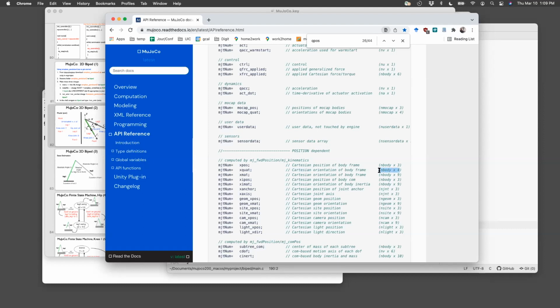And it's basically 4 numbers. In fact, the way quaternions are is that there's one number which is a constant, the first one, and the remaining 3 give you the non-constant part, so qx, qy, qz. What I'm going to write here is some code which will take the quaternion and convert that to Euler angles. So it will give me 3 angles, and those correspond to orientation about the x-axis, y-axis, and z-axis.